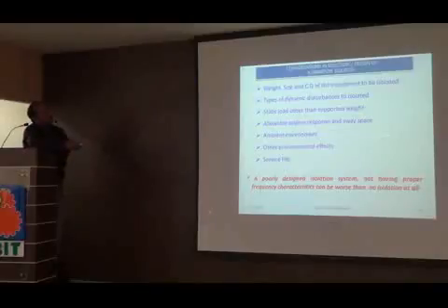And then if these isolators are made of rubber, the environment plays a major role. You should know the rubber behavior at different temperatures. And then the service life is one of the other things affecting the isolator. See, a poorly designed isolation system, not having the proper frequency, can be worse than no isolation at all.